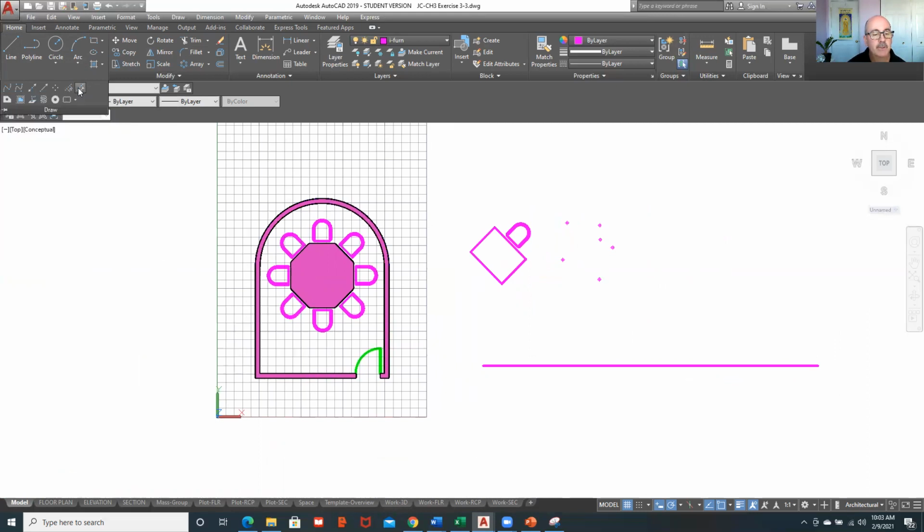And if I say measure, select the object to measure this line. And then the length, I'm going to say 8 feet. Every 8 foot, it'll put a point there. And then I can say how many sections of fence I need. 1, 2, 3, 4, 5. And it works really good on arcs too, because those are more difficult to measure.